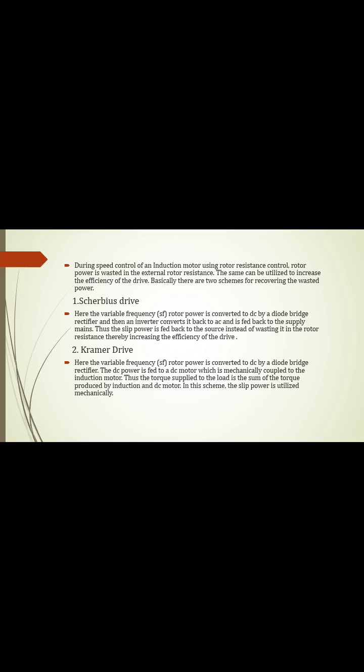In Scherbius drive, the variable frequency rotor power is converted into DC by a diode bridge rectifier, and then an inverter converts it back to AC and is fed back to the supply mains. Thus the slip power is fed back to the source instead of wasting it in the rotor resistance.